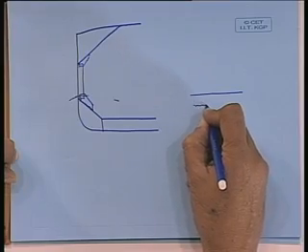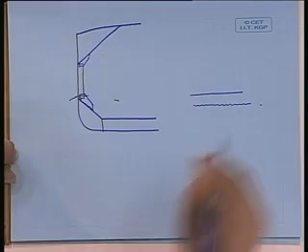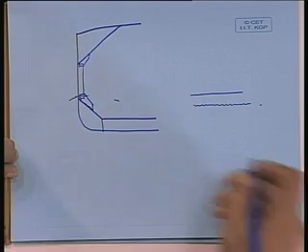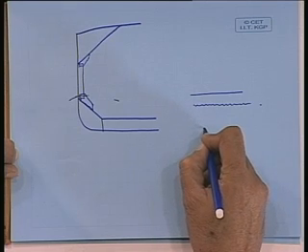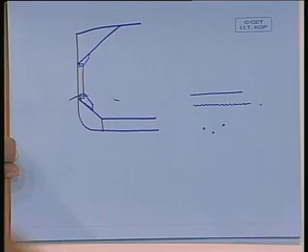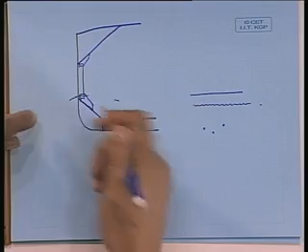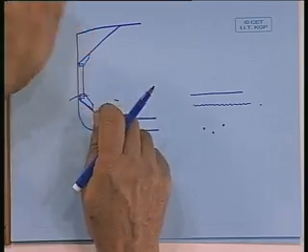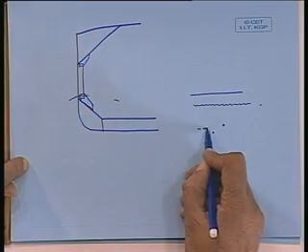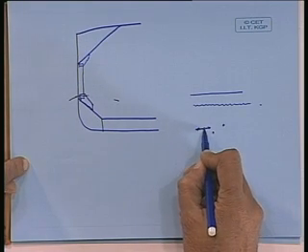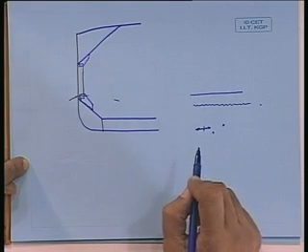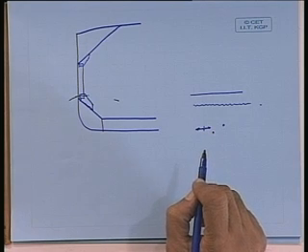The effect of the corrosion is that a smooth surface like this becomes a surface like this. Now, if you see the surface top, each dent here is nothing but a pit hole here, and when this is subjected to some bending, there is a tension here, and tension means at this part the stress is going to 3 times the surface stress.